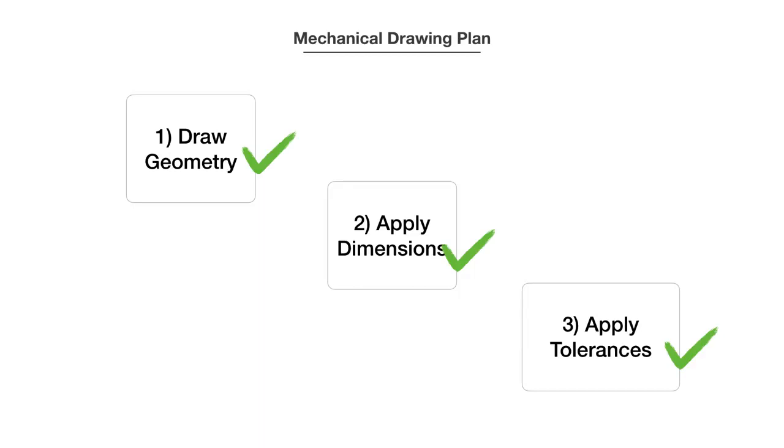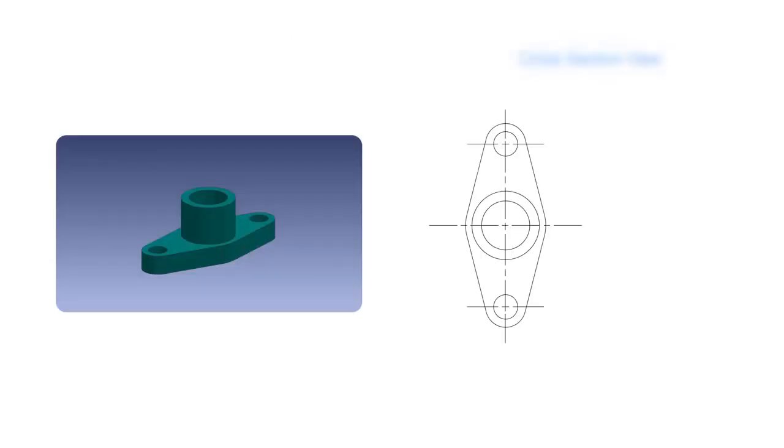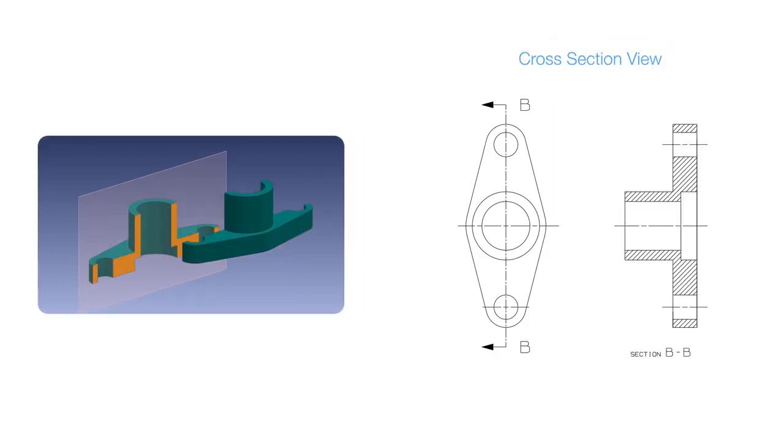Now that we're done with this drawing, let's flesh out our mechanical drawing toolkit with some alternate views that are better at showing certain features. First, I'll talk about a cross-section. Sometimes it's good to see the inside of a part. So you might imagine a plane cutting a part in the region of interest. Here is that flagpole holder part from earlier. And then you have the plane, called the cutting plane, and go slice it open.